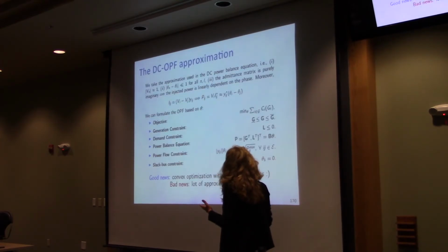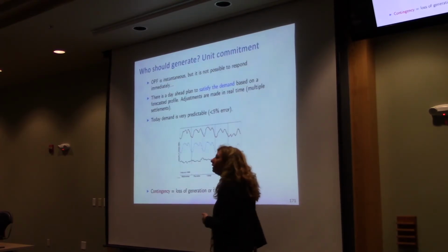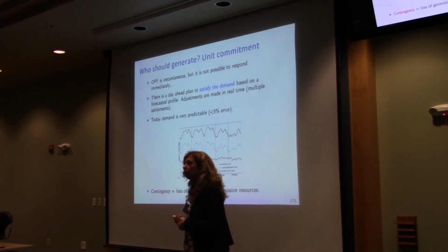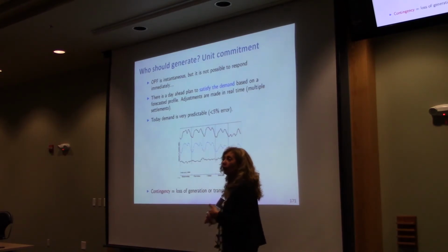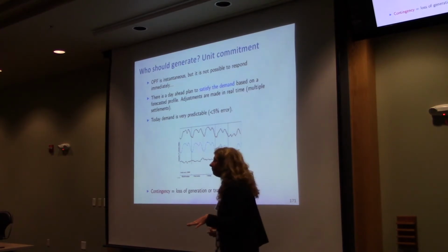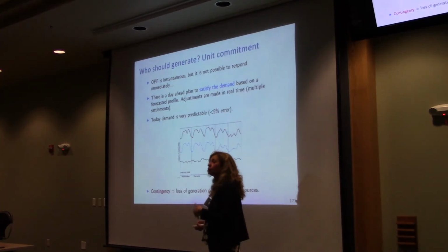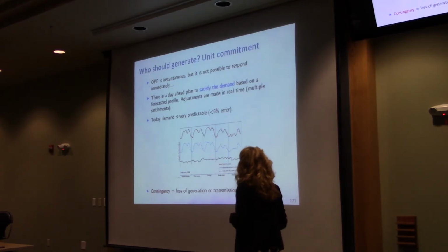So who should generate those? Here, this fleet is decided, this set G is decided. Do you need all the generators you have? What do you think? The answer is no, because in California you need more in the summer than in the winter. So you typically have excess generators, in excess of what you're actually going to use that day. So you're also able to choose who you're going to use. Generators give you a flat cost for just turning them on, and they want the ISO to decide which of them should be turned on, and then the bid characterizes how expensive they are, okay?